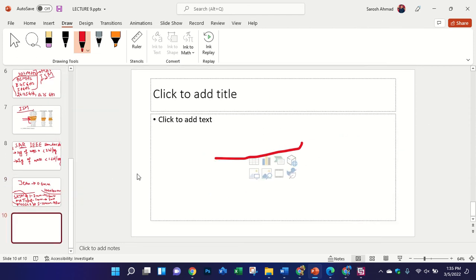Because in some articles I found, they put 0 degree for E-plane and 90 degree for H-plane. So they confuse me. Can you send me those articles? I am not sure, maybe they made a mistake, or maybe sometimes they are not for co-polarization, because maybe they are calculating cross polarization, which is different. If you want to calculate co-polarization, then for the E-plane phi is equal to 90 and for the H-plane phi is equal to 0. But if you want to calculate the cross polarization, then it is the inverse of co-polarization, and you put the E-plane equal to 0. Yes, maybe because of this.